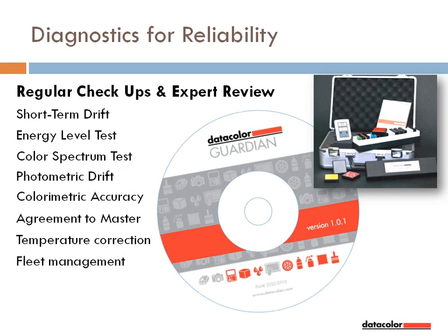Diagnostics. Each manufacturer recommends regular maintenance and diagnostics to ensure proper function of the instruments. Regular calibration and a product like Datacolor Guardian use stable test samples, usually ceramic or porcelain tiles, to verify performance. Datacolor Guardian also includes automatic email and review of regular diagnostic tests by professional service technicians to help discover signs of any misbehavior and correct them early before they lead to product defects and unreliable color measurements.